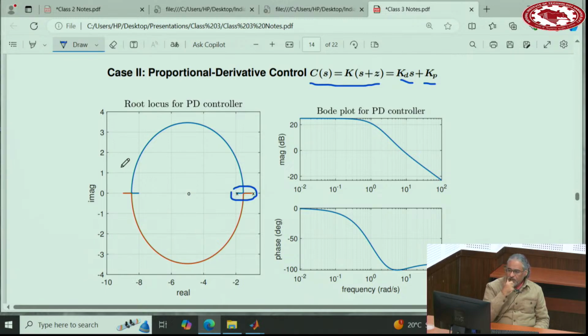But at the same time, if you watch the phase margin and gain margin, you will see that you immediately start losing phase margin and start losing delay margin as well. Very reasonable. And that's why I said in the converter, if you make it faster and faster, your delay margin goes down. So it's a trade-off between how fast I want my responses to be and how much delay margin I can sacrifice.